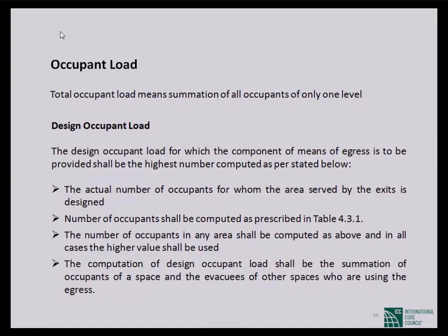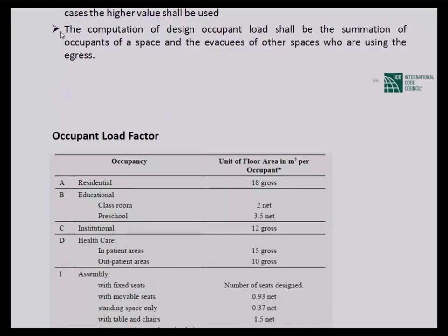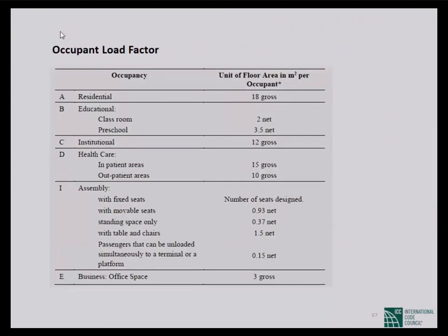So the total occupants that will be served by the exit component considered, that is the actual occupant load. This is the occupant factor. You see that for residential it is 18, for healthcare it is 15, and so on. There is the occupant load.